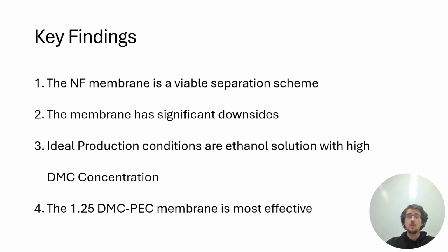This is a significant accomplishment and should be the largest takeaway from the paper, but that does not mean that there are not still negatives with the membrane. While cost is low and separation is precise, the selectivity of the needed molecules is still relatively low. This is a significant downside to the membrane, especially in a large-scale operation, that may prevent it from replacing its contemporaries as the most commonly used separation scheme for amino acids and peptides.